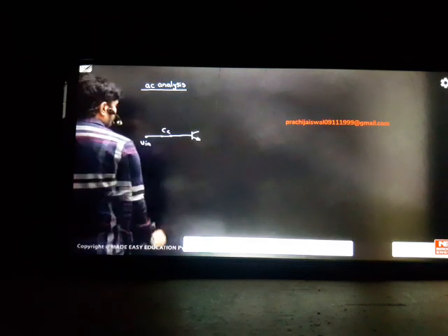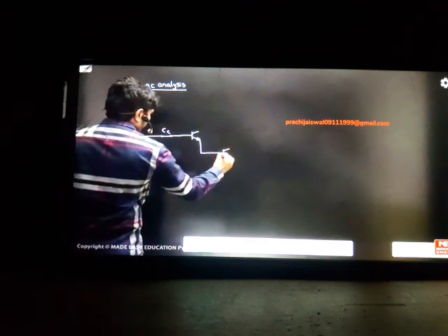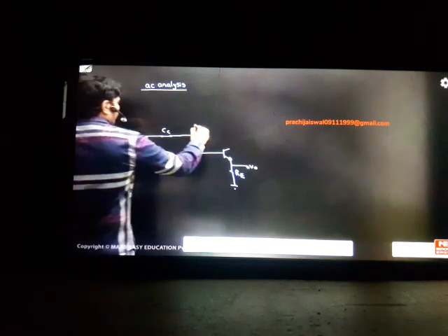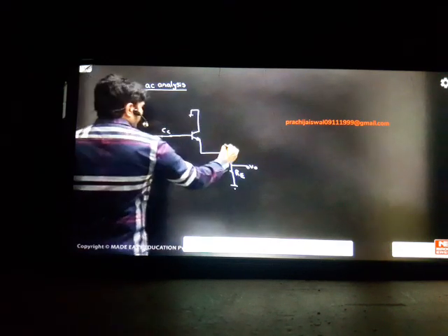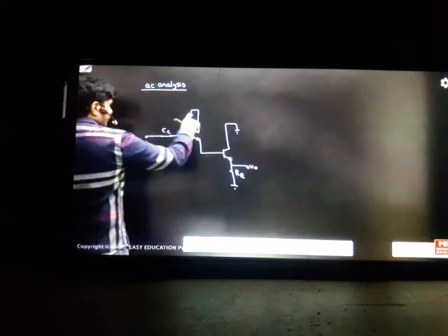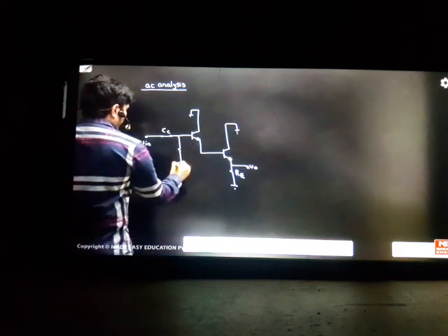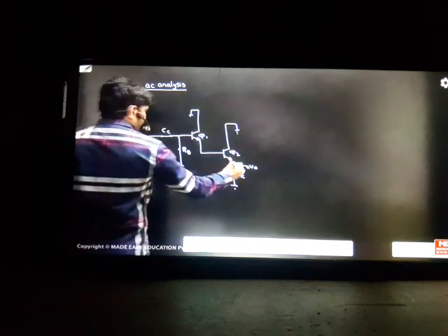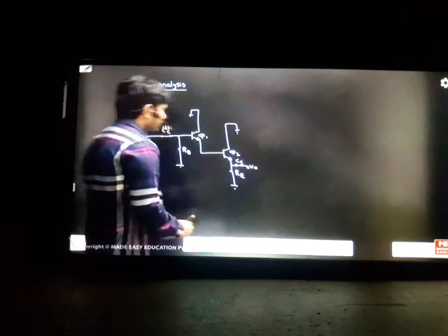First have the rough diagram. What are the things you have changed in the AC model is the capacitor here CC is becoming short. Next we have the transistor, which is connected to one more transistor, and we have the load RE. We have taken the output here V0, and this point became ground and this point also became ground because VCC should be grounded, so both are ground. The biasing resistor will fall to ground this side. So this is called an imagination, how to understand the model, AC modeling technique. These two capacitors are shorted. So I am seeing a model like this.